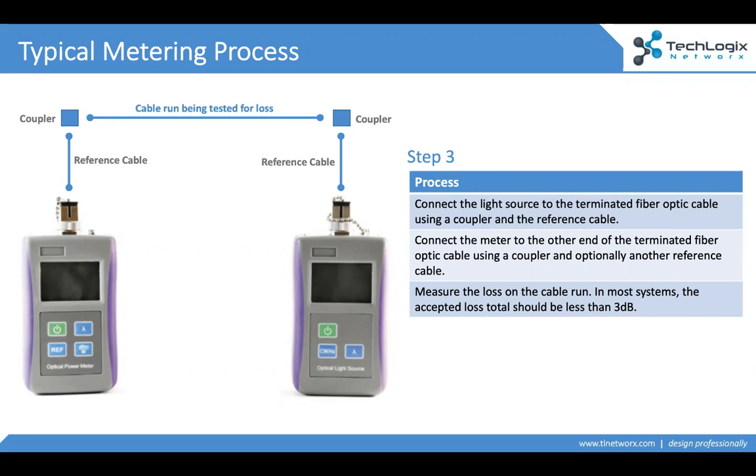Reference cables are nice because they're cheap, they get dirty, they get broken. You know, things happen with the connectors. You can replace those for a couple of bucks. What you don't want to do is get in the habit of taking your main trunk cables and constantly patching them into, you know, dirty test equipment or dirty couplers or things like that.